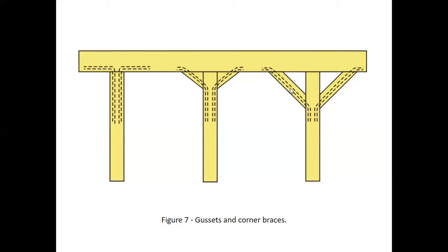You often see these out of a 4x4 piece of steel, square tubing. And you'll weld all four sides there, and that helps create some nice even flow and strengthens this joint itself. It gives a lot more stability and rigidity across the span. So it's a lot more likely to take stress better.